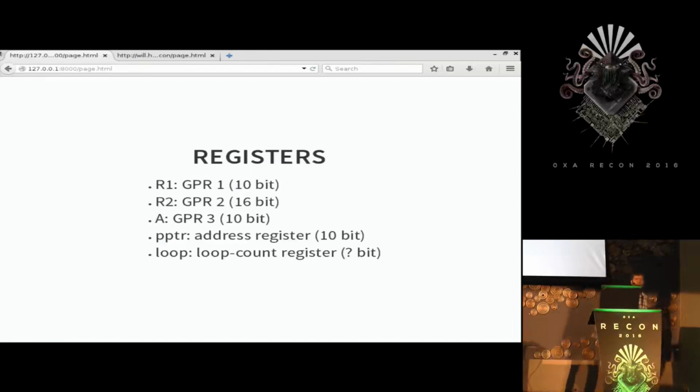And there's also two really weird registers, one of which is a packet pointer register, which is a sort of a register indirect access with hardware base offset based on the current packet it's busy spitting out the RF transmitter. And there's also a specialized loop counter register, which is only ever used by three instructions, which is set loop counter, read loop counter, and decrement and jump if not 0. So that particular register isn't touched by anything else. So it's sort of weird down at the instruction set level.